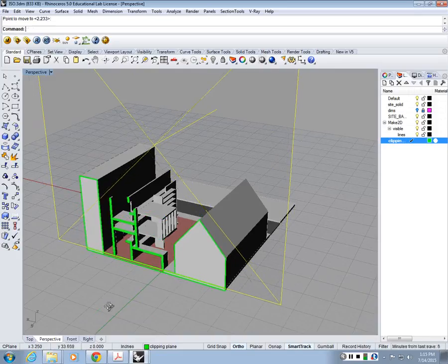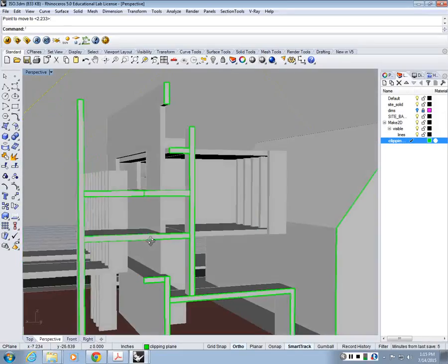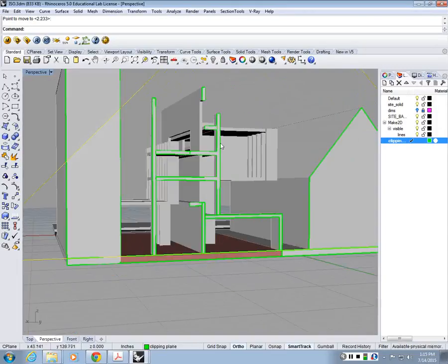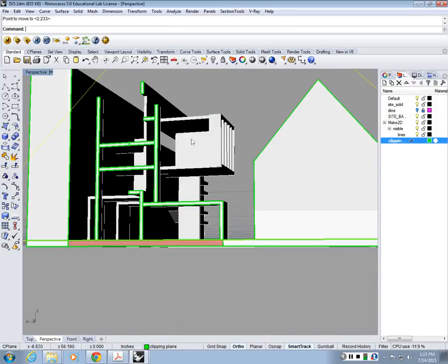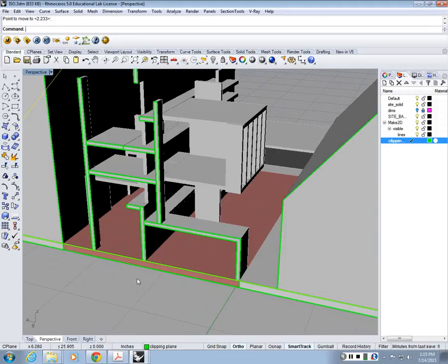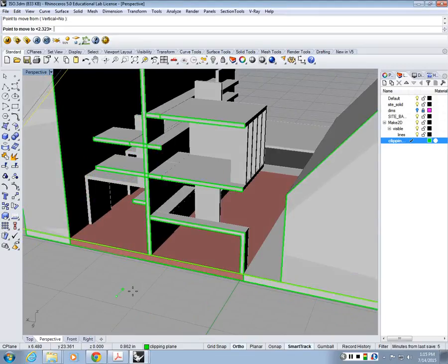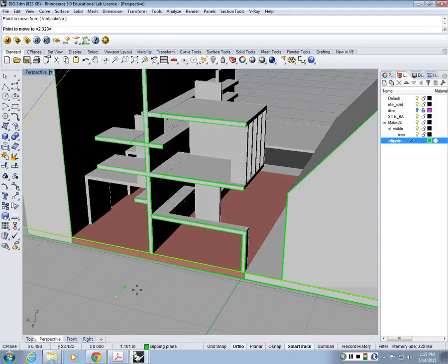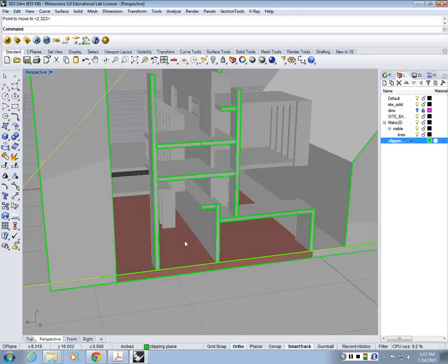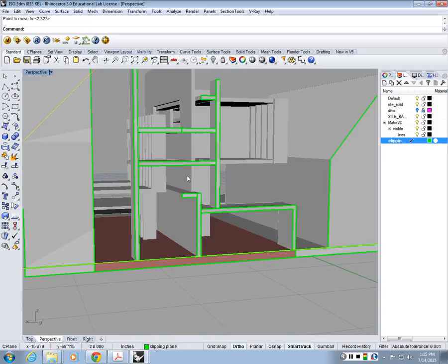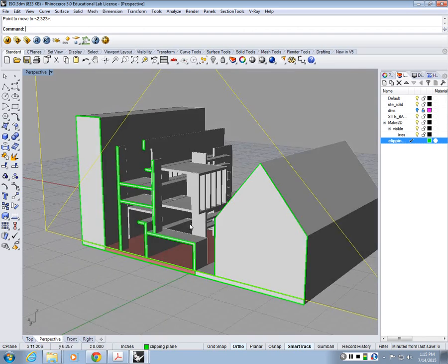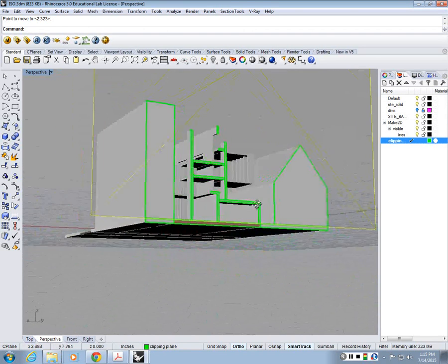The other thing is, most of the time, you want to show openings as much as possible, as well as structure, right? Structure we normally show in sections as slabs, and we maintain some of the vertical main walls. But you want to also show as much openings as possible. So I have an opening here, but then I cut through the wall, and it's a similar situation here. So I'm going to go with this section so that at least I have this opening and this opening in my section, and I'm cutting through this wall here, which is fine, right? So this is the section I want to use.